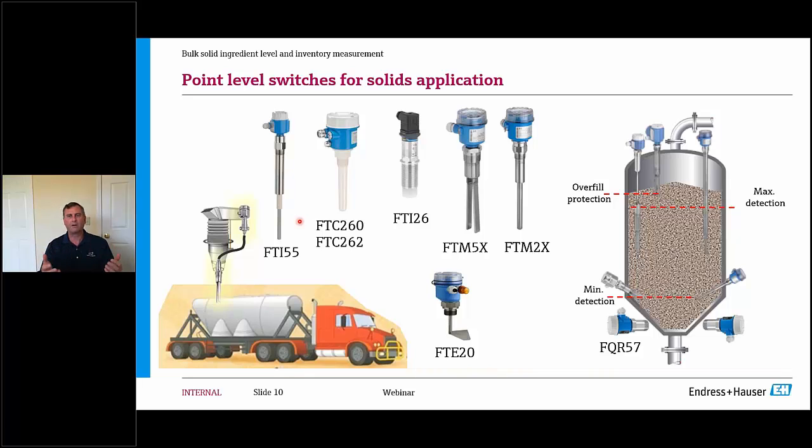So depending on where and how you're using it, you have choices and options based on the product, the size of the vessel, and also what kind of budget you're looking at. Paddle switches are generally one of the more cost-effective ways of doing it. The trade-off with a paddle switch is that it's a mechanical paddle going around, so potentially there's more that could go wrong with a mechanical motor turning a paddle than you would have with a capacitance or a tuning fork style, where there are really no moving parts.